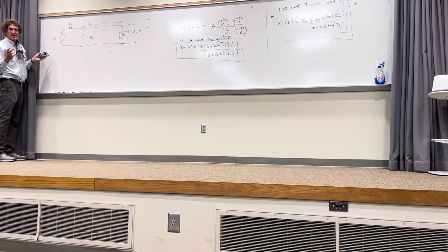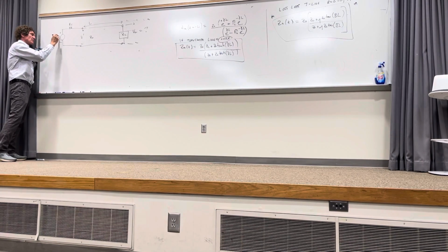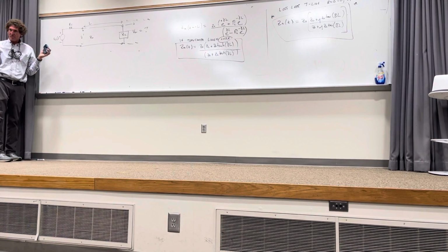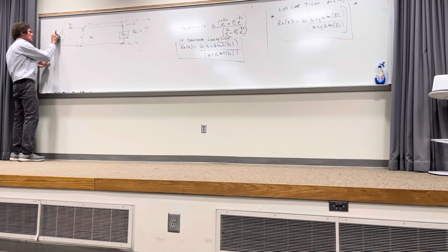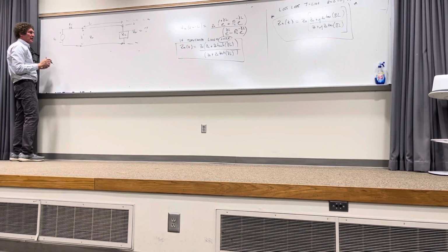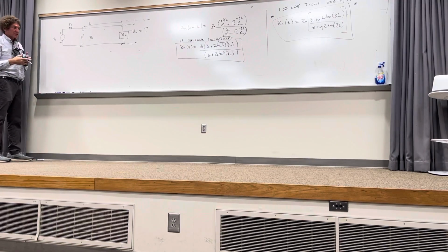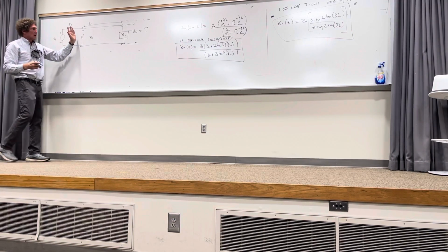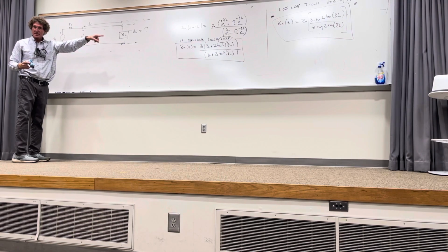Now, I'm assuming it's in a phasor form, so I could put Vs at an angle of 0 degrees, but it doesn't mean anything. Y'all follow me? I'm just going to leave it as Vs. Why write the 0 if you don't have it? It's a magnitude. So that's just got a magnitude of Vs, but I want to find out how much voltage is developed right there. And the way I do it is, I replace all that by the input impedance I just stated, that's Zin.